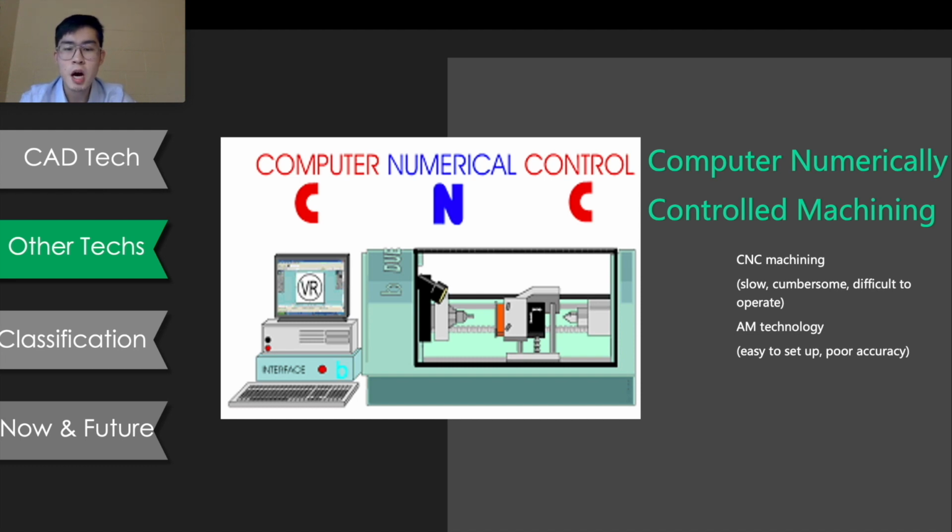So for geometry that can be machined using a single setup orientation, CNC machining is often the fastest method. For parts with complex geometry, which require a large proportion of the overall material volume to be machined away, AM can be used to more quickly and economically produce the part than CNC.